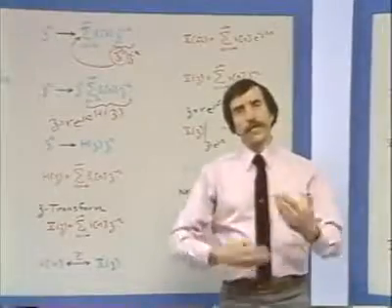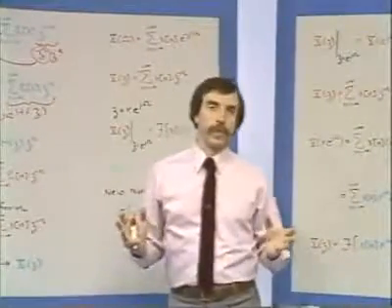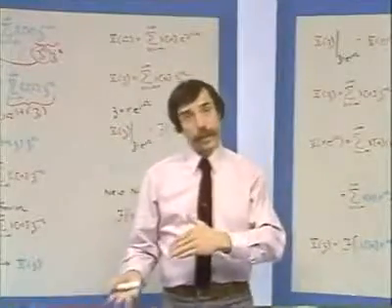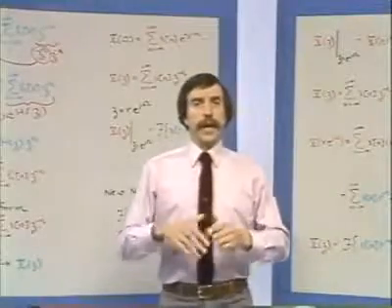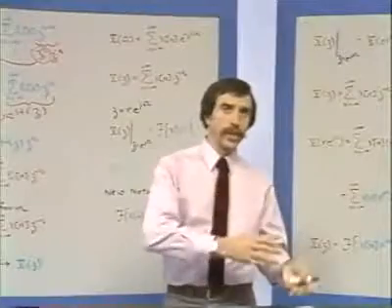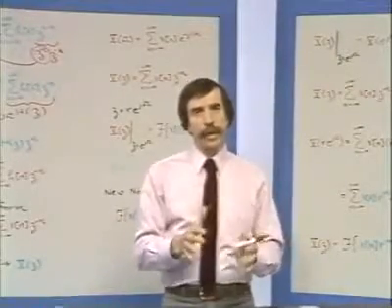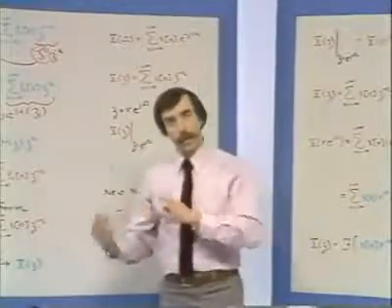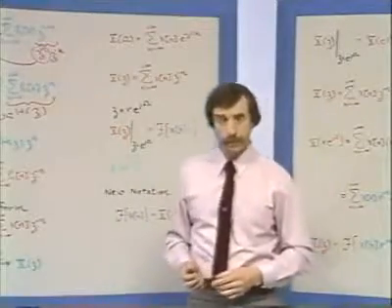All right, so we've motivated the development in a manner exactly identical to what we had done with the Laplace transform. The idea is that if you look at the eigenvalue associated with a linear time invariant system, that generates a mapping between the sequence, the system impulse response, and a function of z, and that corresponds to the z transform here.